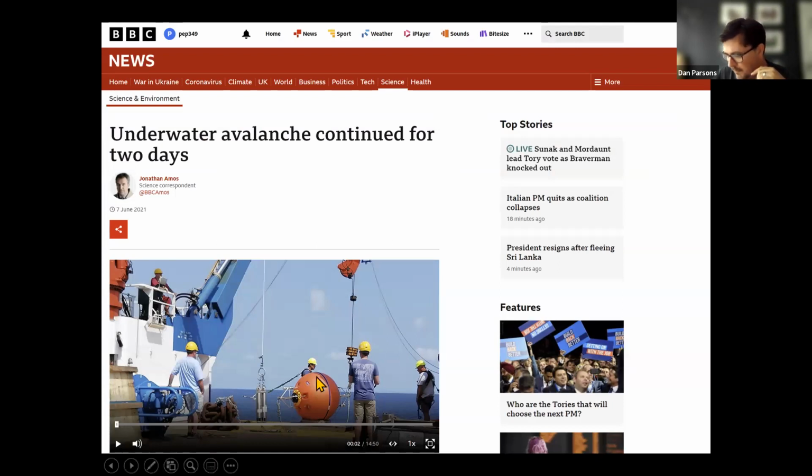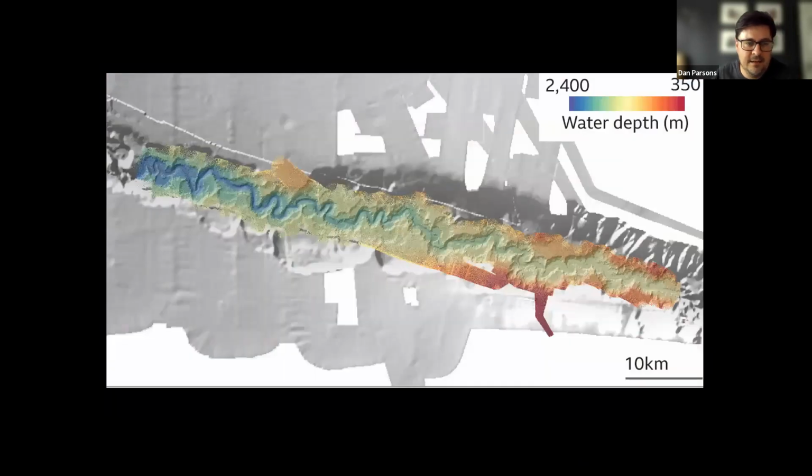But you can see here quite neatly, it's probably a better photo than anything I've got, one of these mooring systems: the bottom-looking ADCP on a mooring line with a series of floats, with a big chain as the anchor onto the seafloor, and the silver thing hanging in the middle is an acoustic release, which would allow us to recover the ADCP by sending a signal down, and that system would then release from the weight and pop up to the surface. That was the plan. I'll come to that in a second.